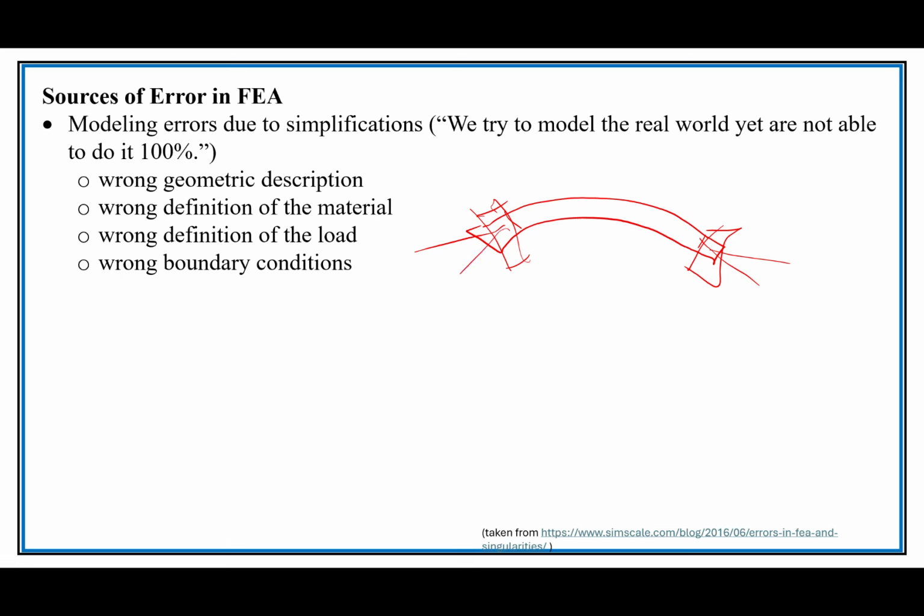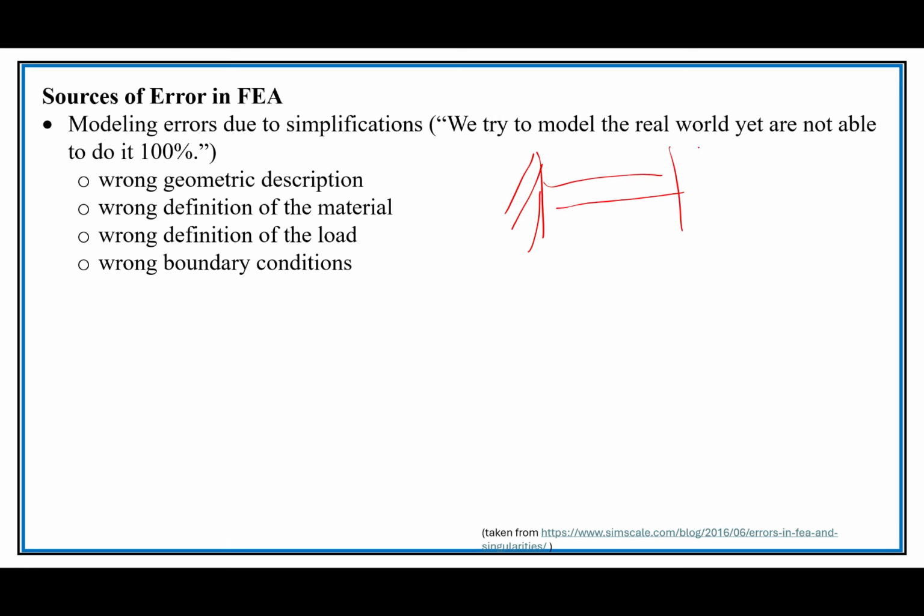And so you can't just put boundary conditions onto this region and hold it tight and get the correct results, because it would treat it like it was fixed, like this right here, like there's the original conditions right there. It would make it rigid here at the boundaries because of the boundary conditions you chose. And that would not model what the correct thing would be in the real world.